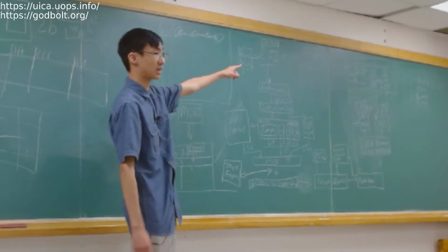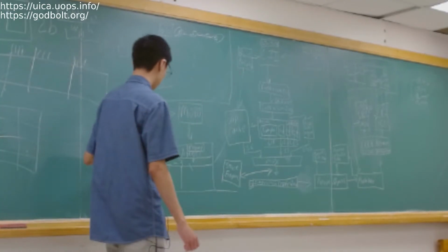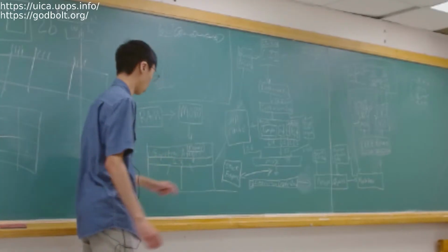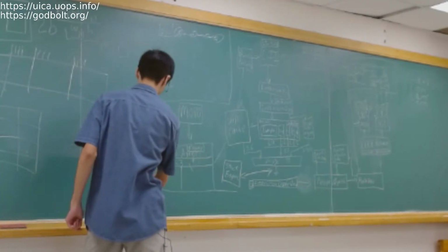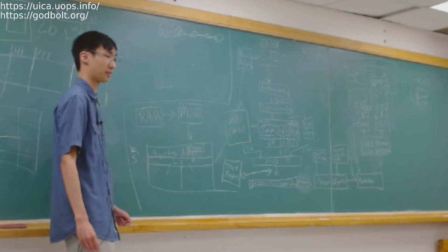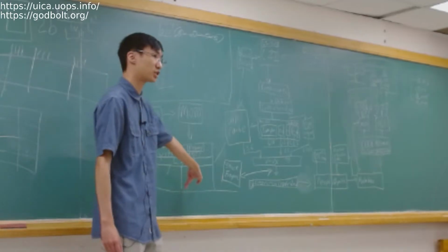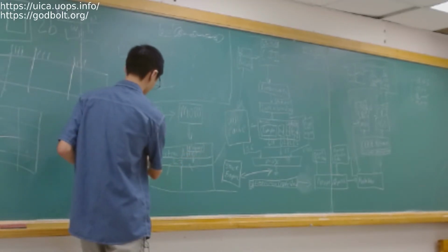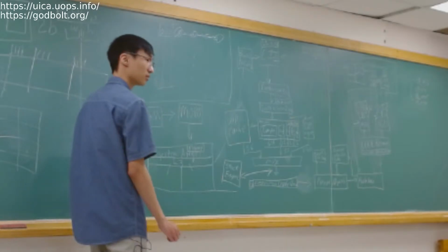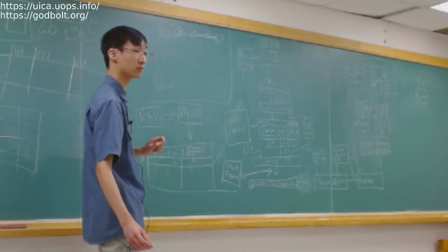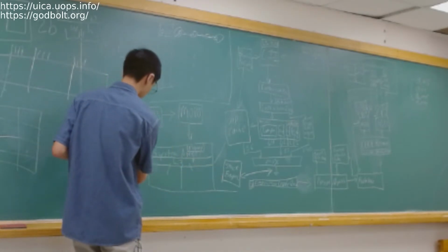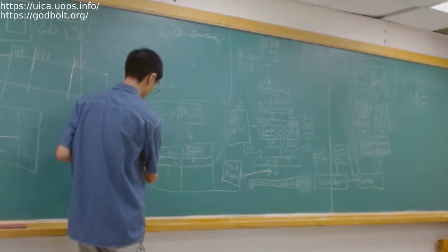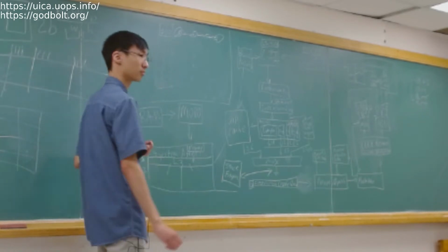So a line in the cache will become exclusive. And then if that line gets stored by another core, then we remove that exclusive and we call that line shared, right? And then once it's shared, we go, okay, well, if one of them modifies it, then you call this one modified, and then you call this one invalid, okay?